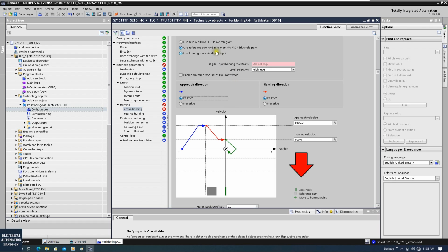Then it's searching for the encoder zero mark from the encoder. And once it sees the encoder zero mark, it records that position. And maybe the drive still needs a short distance, just very short, to stop. But at the moment, the drive internally records that position already. After it totally stops, the drive can move backward a little bit, back to the recorded position from this zero mark. Meantime, it will zero or set a value to this position. This is the real home position.